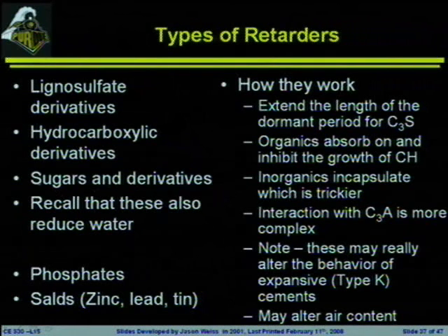Sugar is a fairly typical type of retarder, or the derivatives of sugar. You'll also see some lignosulfonates, some hydroxycarboxylate derivatives. You'll also see some things like phosphates being thrown into the system. Again, they're typically going to work on the dormant period of C3S. They're going to extend that out a little bit.